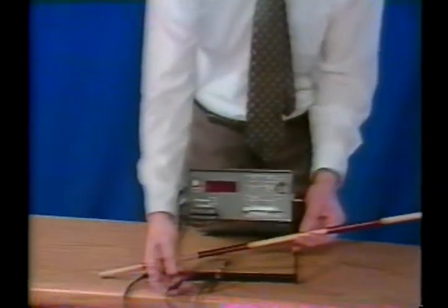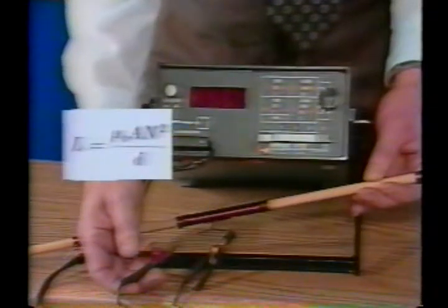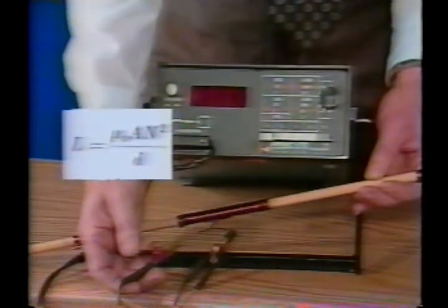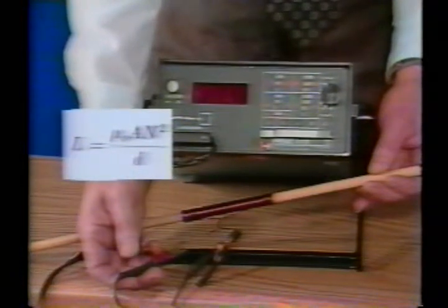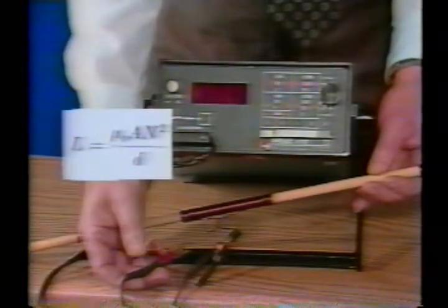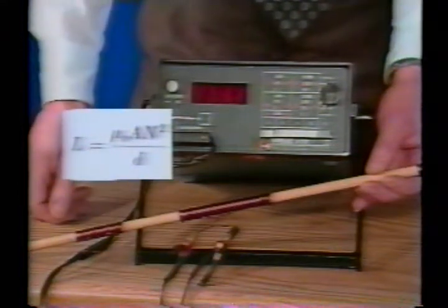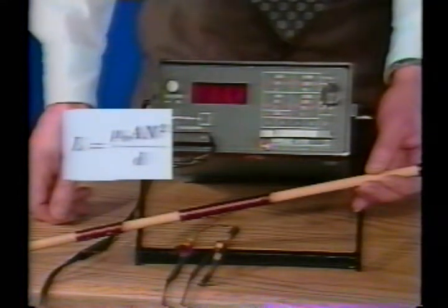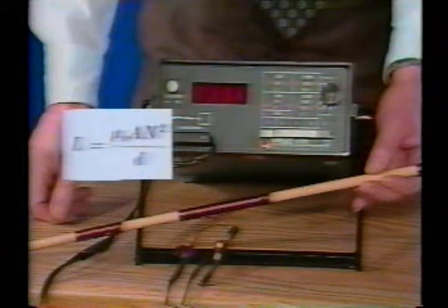We now measure the inductance of the coil, which is the same length as the second coil, but has 2 layers of windings and thus double the number of turns. We measure 44.4 microhenries, for which the corrected coil inductance is 43.7 microhenries. We have doubled the number of turns without changing the coil length.